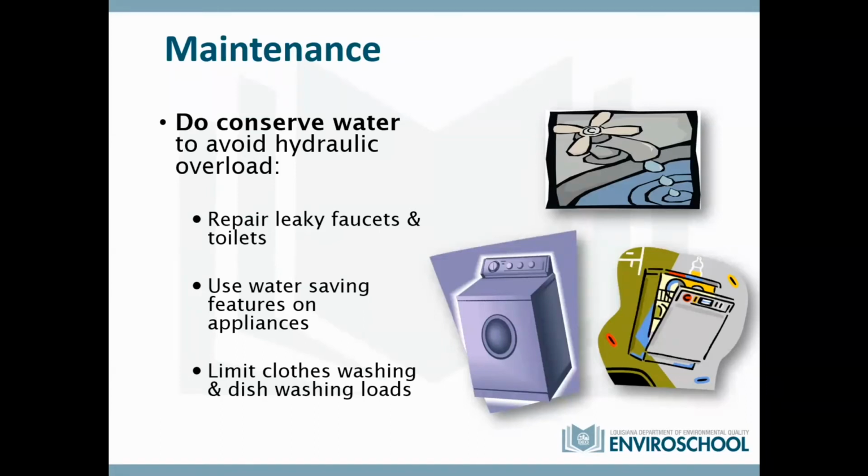Now these systems are made specifically for a certain amount of water for the certain property that it is designed to treat when it was approved by the Louisiana Department of Health. As such, they cannot be overloaded. If you hydraulically overload these systems, they're not going to work properly. You're not going to be treating the sewage because they need time for the bacteria to work on it. And so basically, if you understand what the term bypass means, you'll be having your own little bypass going on and discharging untreated effluent, untreated sewage into the environment around your house.